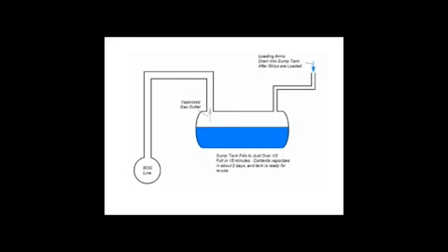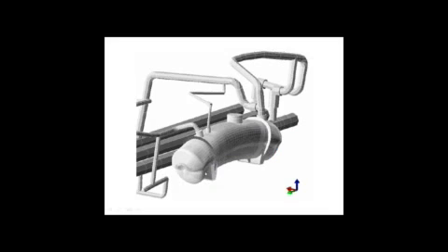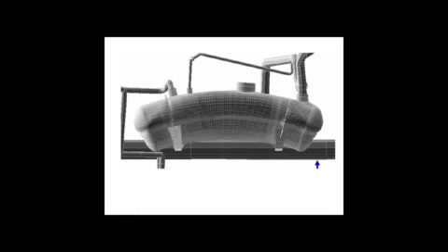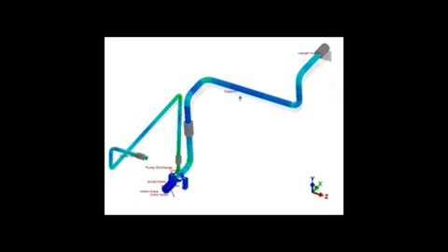All right, here's another model. This is an example where we've got a vessel. You say, well, why am I worried about a vessel? Well, if we go to the next slide, what you see is that the piping can definitely move the vessel around. Go to the next slide. You can see that at the end of the system we've got a branch connection coming off the vessel that's definitely bending this very, very large D over T vessel. The FEA technology in FEA Tools is not limited to D over T of 100. A lot of vessels have D over T's greater than 100.